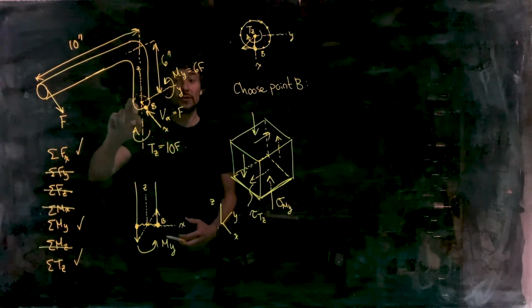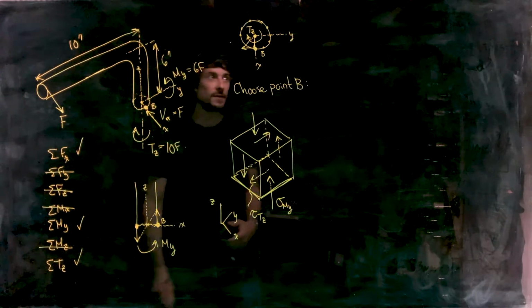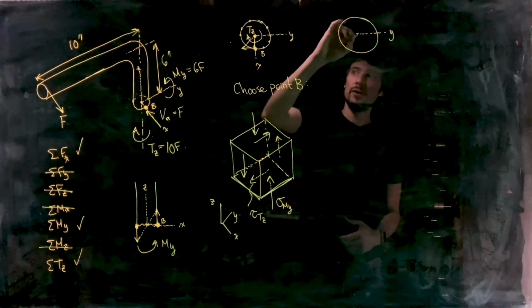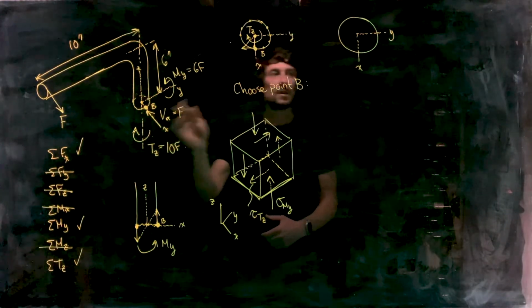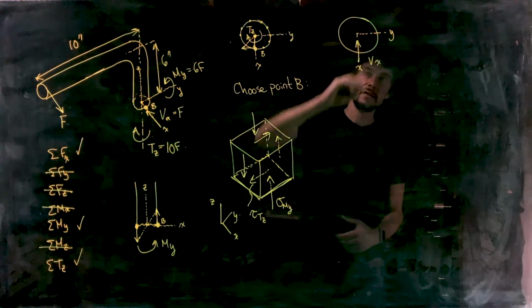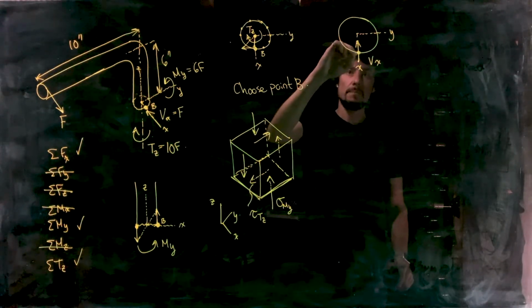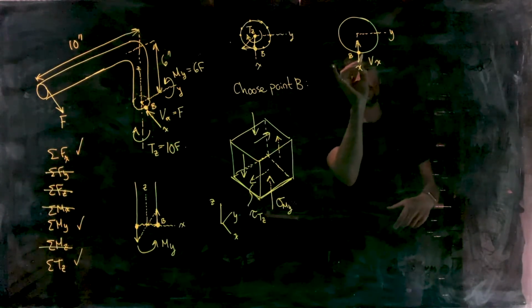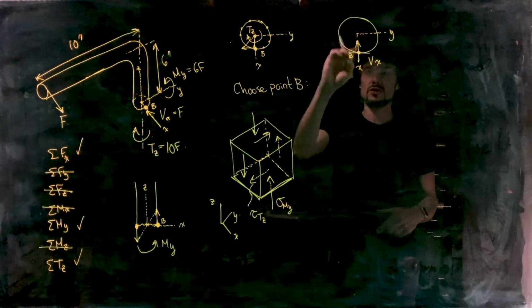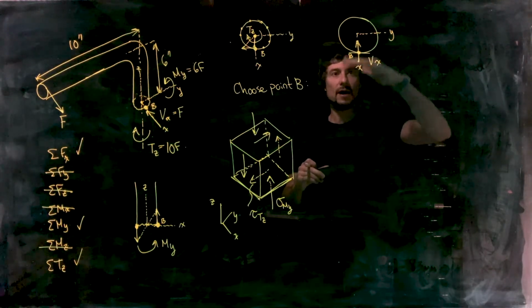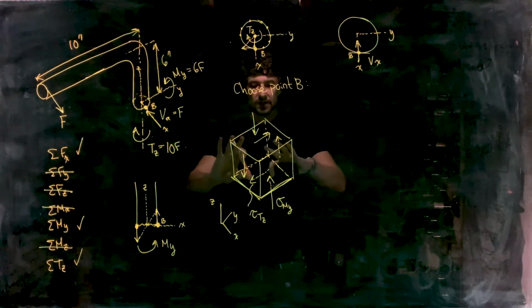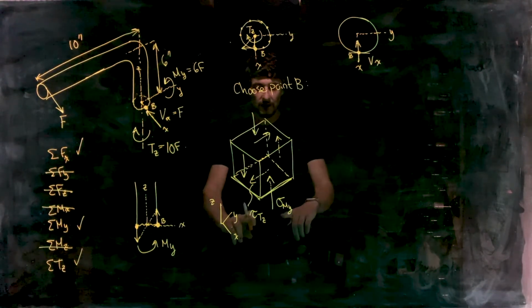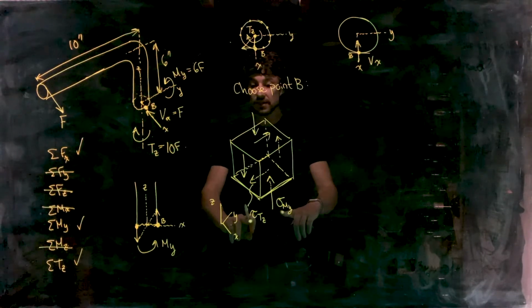For our internal shear force, because we've also got an internal shear force present, remember that if we draw a picture of our cross-section with the y-axis going out like this and the x-axis going out like this, and our internal shear force Vx is in that direction, then here at point B, where we're considering, there is no shear stress due to Vx, because if we were to draw a line through point B that is perpendicular to the direction of the shear force, the area of the cross-section below that line, A prime, is 0. So this is our stress state for our element. So let's go ahead and calculate the values of sigma My and tau Tz.